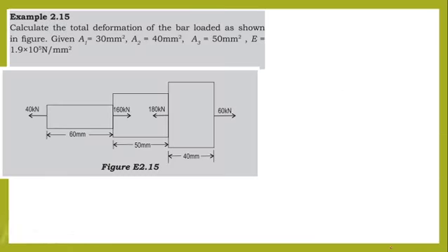So we'll do one more question, so we get a very good idea about this. In this question, the bar has a varying cross section. So we will apply the same principle of superposition by dividing this bar into n sections. I will draw lines at the sections for force analysis. Okay, we'll start from the first section.